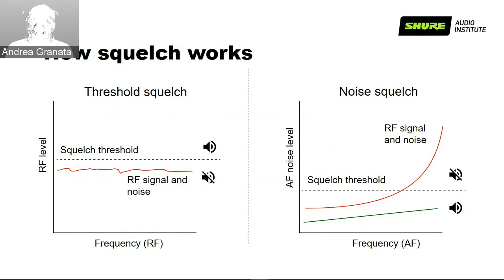It's not just quantity. The squelch evolved and can now be controlled by, for example, the amount of noise that is entering the device. So if my device recognizes that there is more noise than actual signal, and how do we discriminate the noise? By the quantity and the quality of high frequency. Depending on how much noise we have, the squelch can open, meaning letting the signal go, or stay closed.